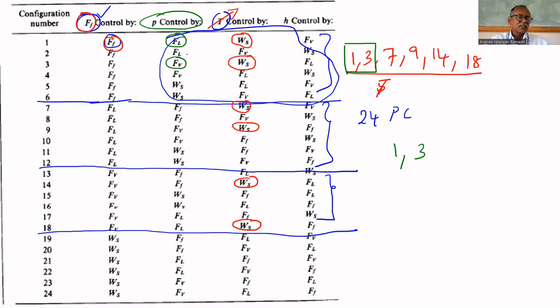That's why pressure will decrease initially. It is indirect effect, not direct effect. But if you use vapor top product flow rate to control pressure, it has direct impact on that. That's why 3 has to be selected.